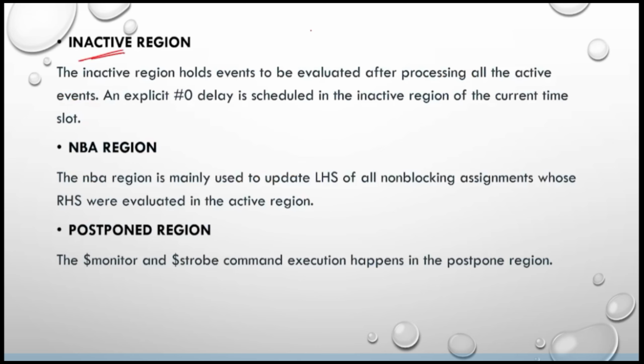Now coming to the inactive region. When you don't give any delay and when you give #0 delay, there is some difference between them. Actually, without any delay and #0 delay are both the same. But when it comes to execution, if you are not giving any delay, that will be executed in the active region. If you are giving a #0, then that statement is executed in the inactive region.